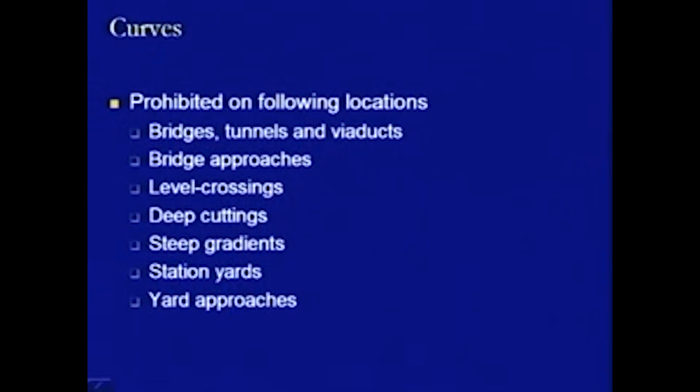In the case of level crossings also, if a curve is provided, it will increase the length of the track on the level crossing section, and this is another hazardous condition. It has safety implications, because the people crossing the railway track have to move longer distances and remain for more time on the railway track. This is not good for their safety.